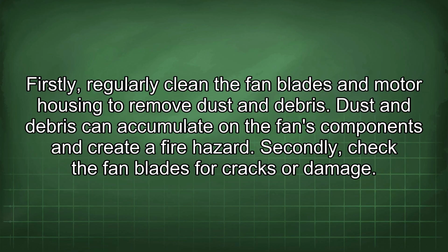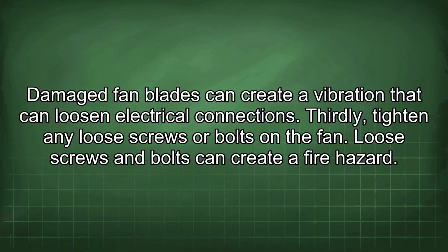Secondly, check the fan blades for cracks or damage. Damaged fan blades can create a vibration that can loosen electrical connections. Thirdly, tighten any loose screws or bolts on the fan. Loose screws and bolts can create a fire hazard.